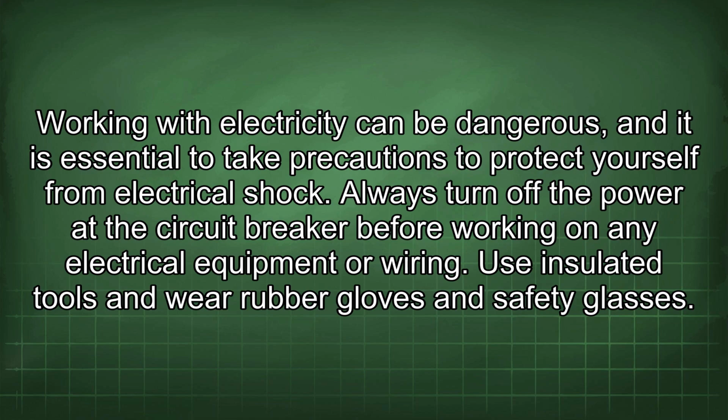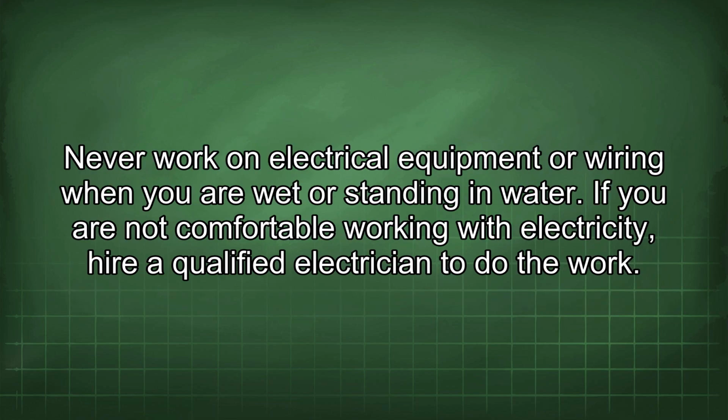Working with electricity can be dangerous, and it is essential to take precautions to protect yourself from electrical shock. Always turn off the power at the circuit breaker before working on any electrical equipment or wiring. Use insulated tools and wear rubber gloves and safety glasses. Never work on electrical equipment or wiring when you are wet or standing in water. If you are not comfortable working with electricity, hire a qualified electrician to do the work.